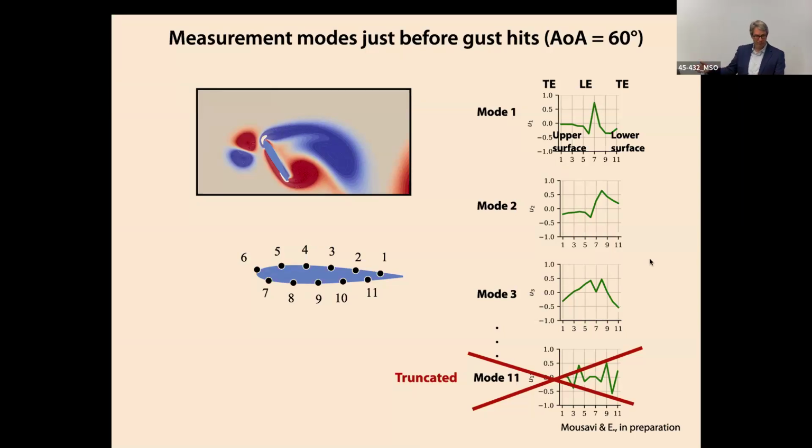We used angle of attack sensors, and that was enough to infer the location of the leading aircraft's wake. From our model, we had an observation model of what those angle of attack sensors should see based on the proximity of another vortex. So my answer is that we've done other sensors, and of course there are other sensors we'll try. We also want to fold this into the flight dynamics, and look at IMUs and that sort of thing. Yeah, it's a good question.